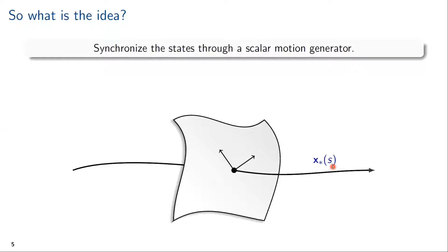It differs from time in the sense that it can be recovered from the states of the system, meaning that if you know the state, so the pose and velocities, or configuration and velocities of the system, then you can find s through a so-called projection operator. This means that for the given state, you can find what the corresponding joint variables should be and their velocities and so forth at any given time. Now this synchronization also has a value in terms of trying to design feedback.